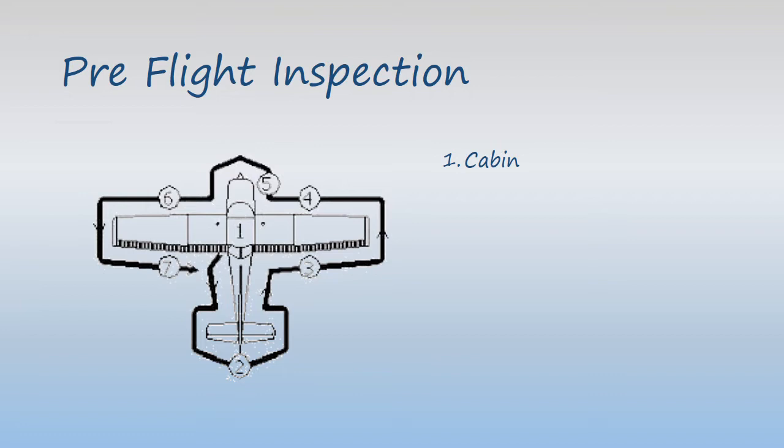You are going to start your visual examination of your aircraft from the left side door and follow the sequence shown in the picture. The purpose of doing this is to make sure of the serviceability of your aircraft, and that there are no loose fittings and no cracks on the fuselage. Then you come to your tail section, where you can check the condition of the elevator and its control movement.